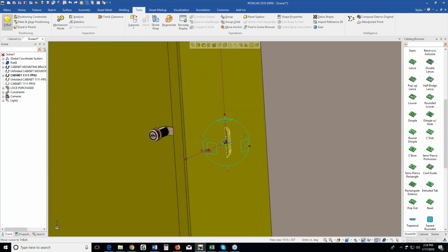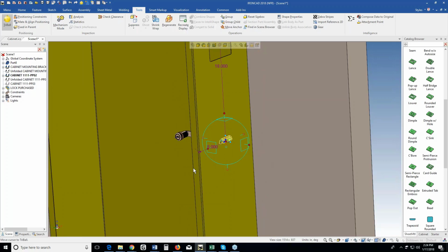We need to rotate it, so I activate my tri-ball. Simply, again, left click the handle and hold on the axis that I want to rotate. I can snap to the face, and that fast I've rotated around 90 degrees. An excellent and very handy tool.